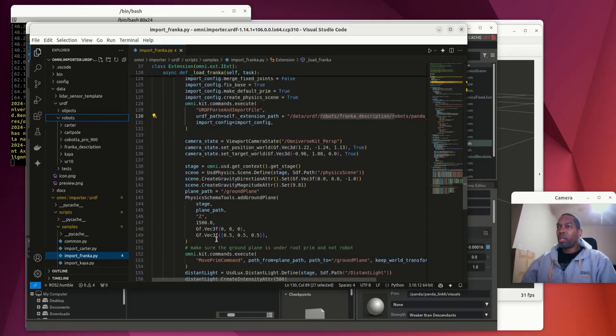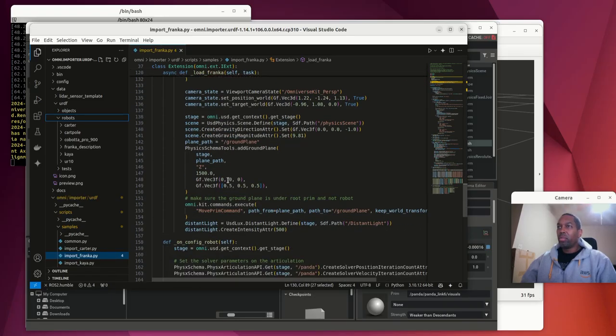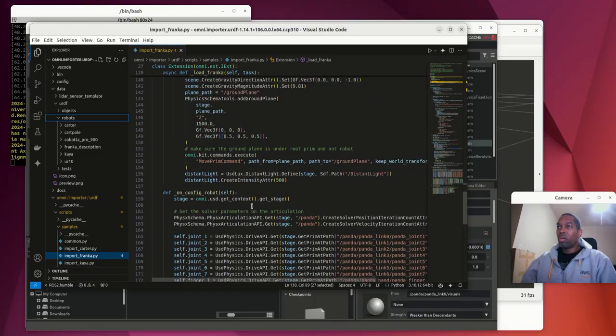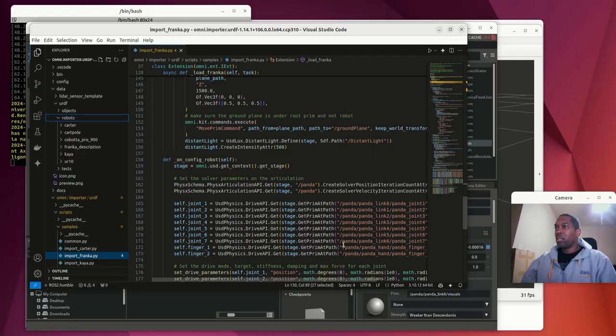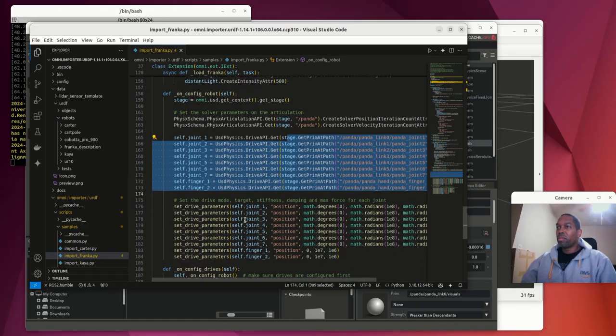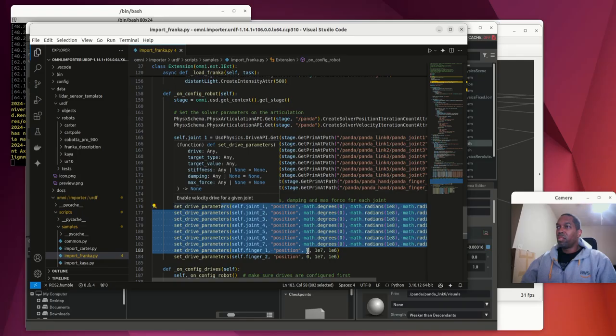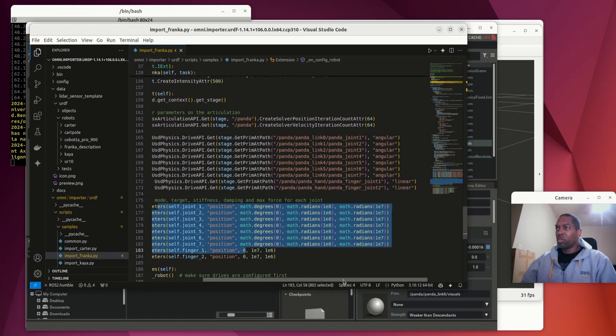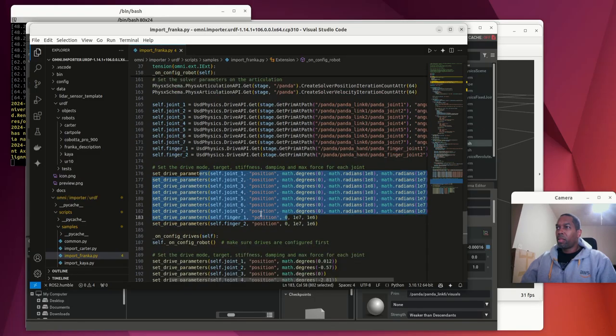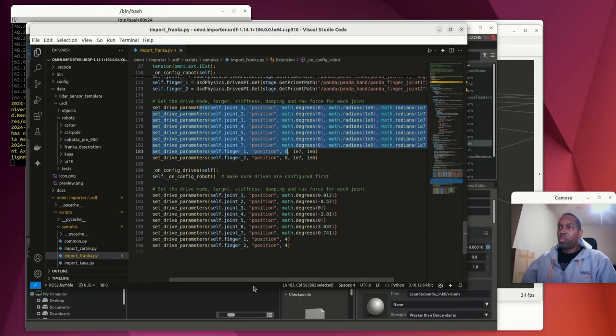All of the Python code is available to me. So if I wanted to take any part of this or all of it, I can go ahead and take it all. Or say I wanted to go headless, then as we looked at with Genesis AI here, these are my joint descriptions, just like we had before, and this is the max force for each joint, stiffness, damping, those kinds of things for each joint. And here I'm saying move the position. So this is very, very similar to what we saw in Genesis, with a little bit less processor being used.